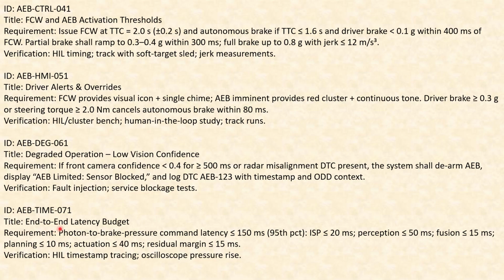Now, talking about the end-to-end latency budget. This is extremely important. Photon to brake pressure. The moment photon means the moment the light ray hits the camera. The photon to brake pressure command latency should be less than 150 milliseconds. ISP less than 20 milliseconds, and perception less than 50 milliseconds.